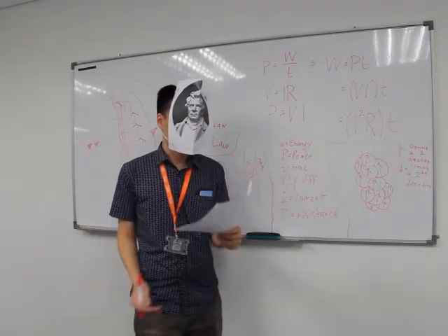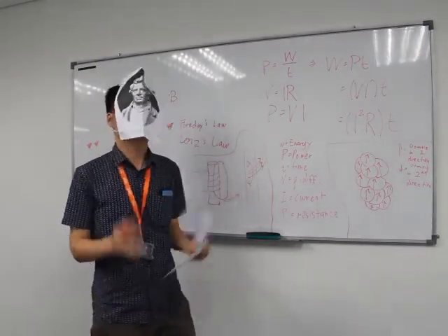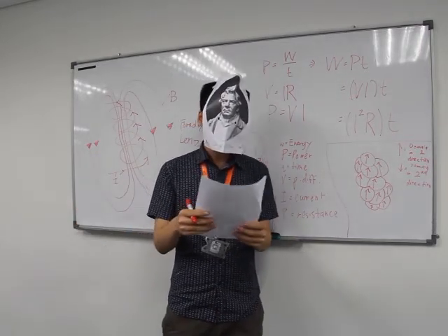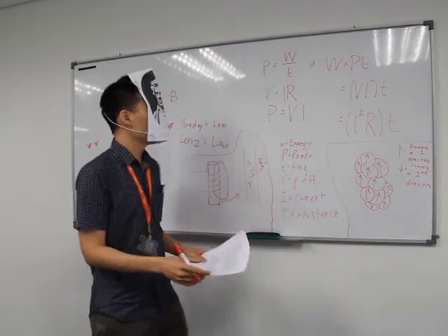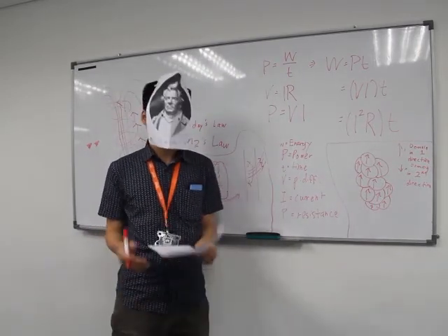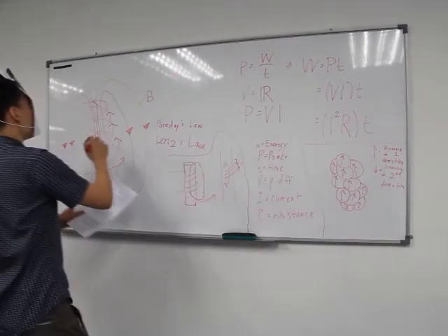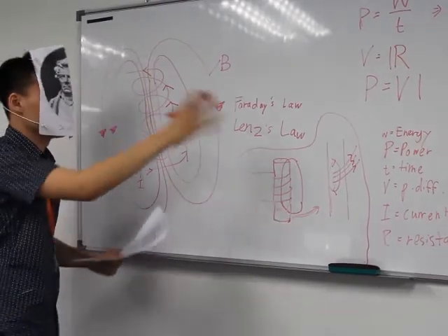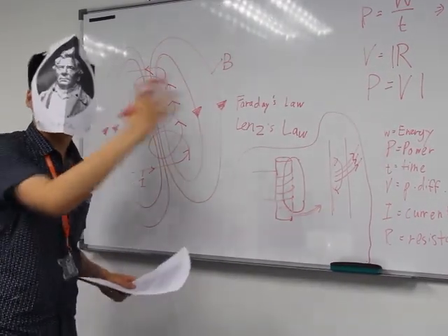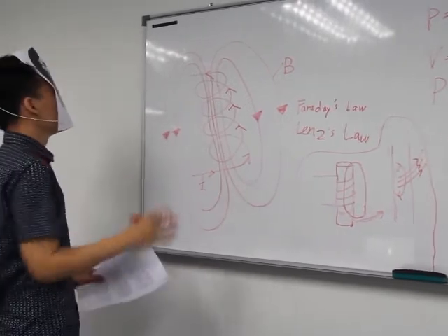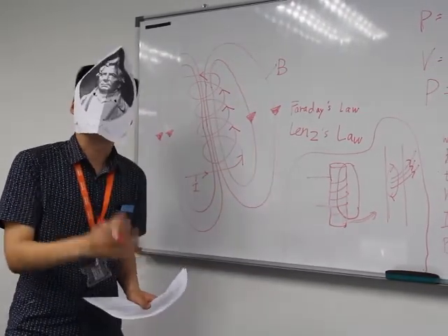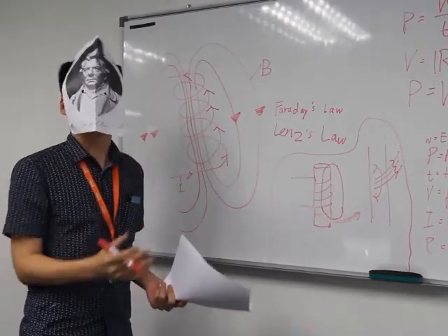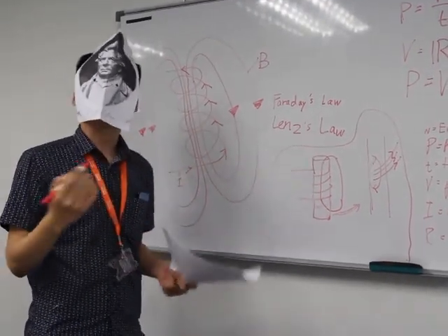Now, as we all know, the transformer that we've been studying is the perfect transformer. But also, as we know even better, life is never perfect. Same goes for the real transformer. The magnetic flux generated by the first coil over here mostly goes through the secondary coil, but only mostly. Some of it will flow back into the first coil, and since the current going through that coil is AC, this magnetic flux going back into the primary coil is also constantly changing direction.